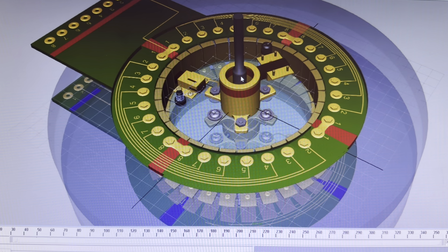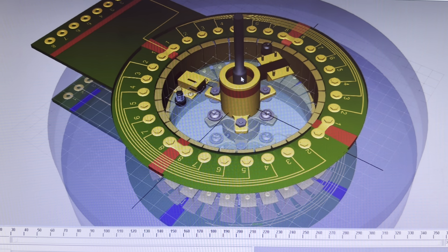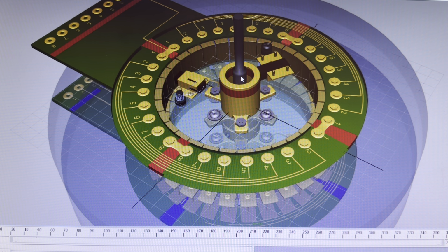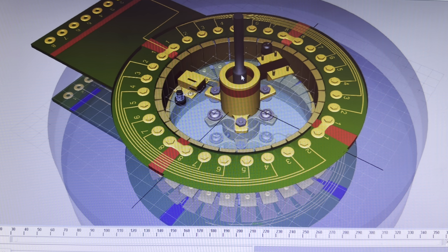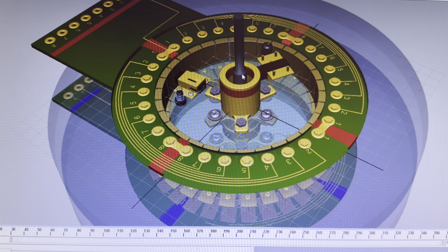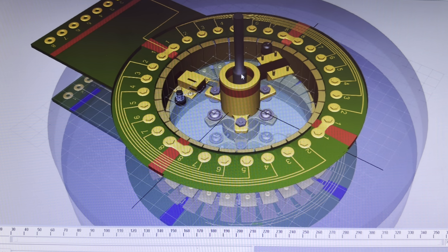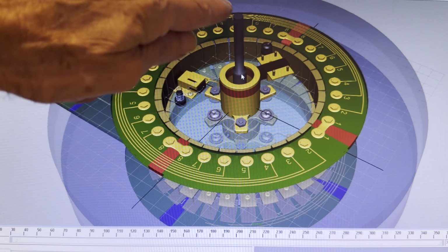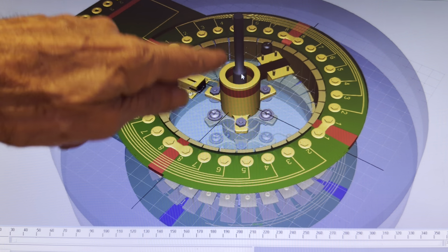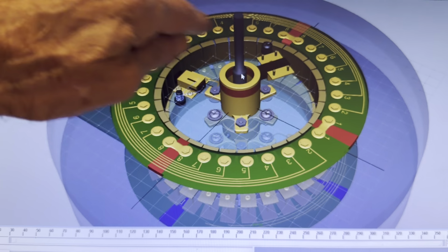So this applies for everything, every machine that has a shaft on it, and we go by looking at the front shaft. When it says looking at the front shaft, it refers to the part of the shaft where we take in the power or input the power of rotation.